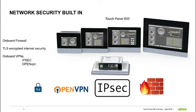We know that cybersecurity is important in all of our applications, and therefore all of the TouchPanel 600s have built-in network security. First, let's discuss the onboard firewall. All the TouchPanel 600s come with two Ethernet ports. These can be configured as a switch or as two independent ports with separate IP addresses. Separating the ports can be an advantage if one port is used to communicate with the enterprise-wide systems and the other port is used to communicate with a control network.